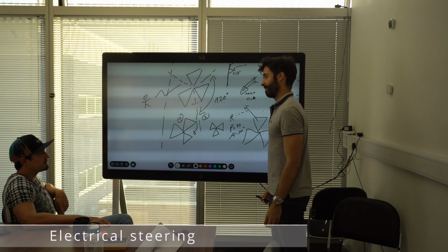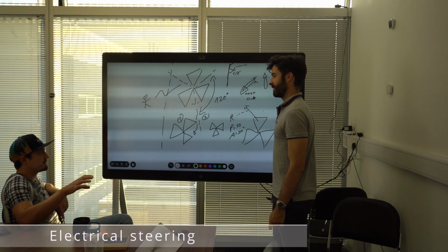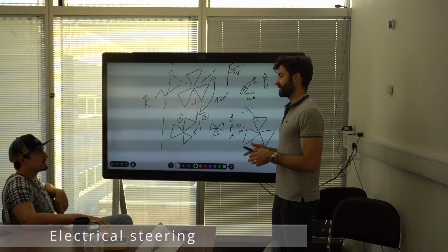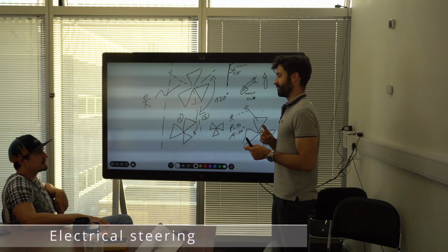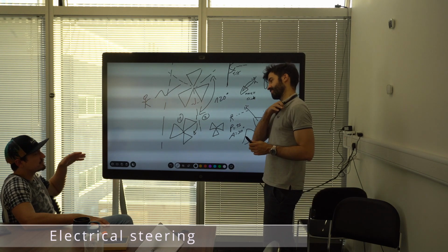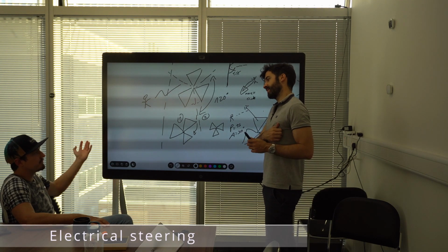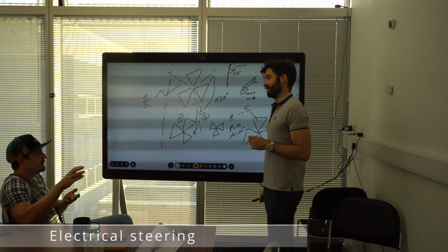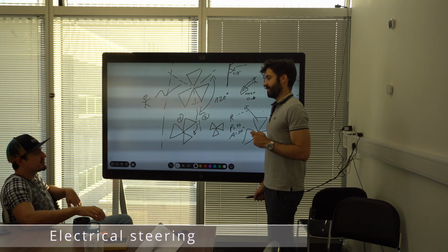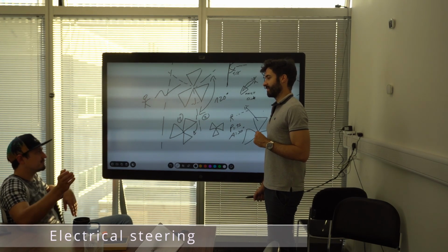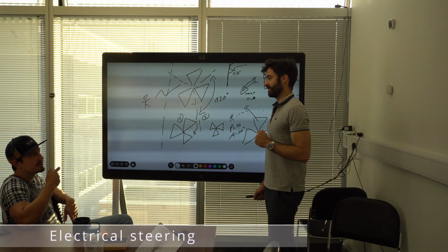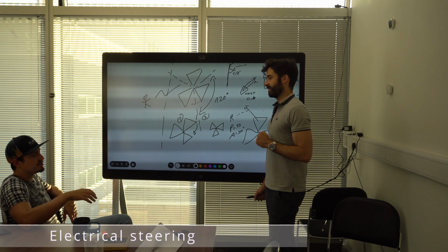Is it at all related to massive MIMO, where you have lots of individual elements that you can control? Yeah, but those are usually active elements and you need to change the BBU to do that. Here it is a simple mechanism. In this case it's just like a reconfigurable intelligent surface. You just enable each unit cell at a time, and you change the phase based on your diode signal, basically. Controlling the voltage to the diode changes the phase.